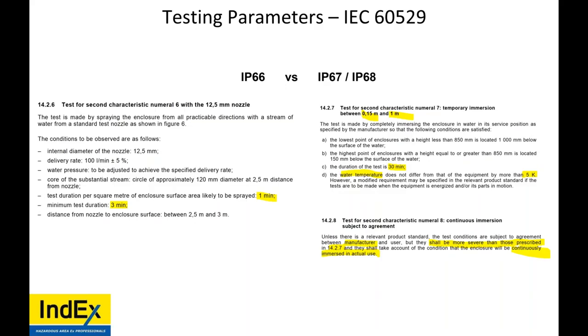Some enclosures, important ones like control panels, have 2 breather drains installed. When it's installed at the bottom, it makes a very good drain. When it's installed near the top, it makes for a very good breather.